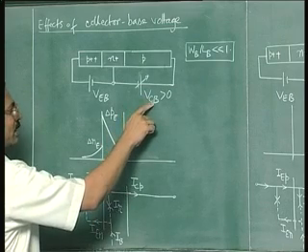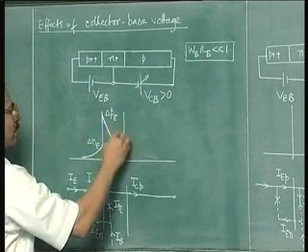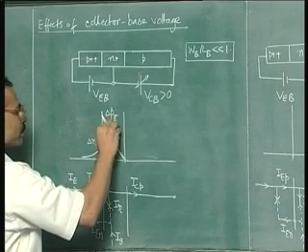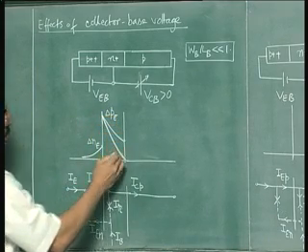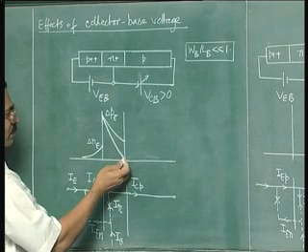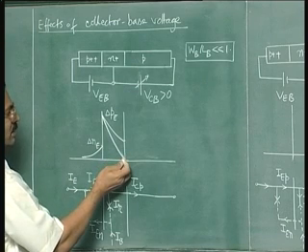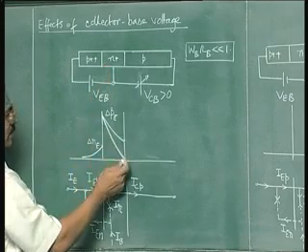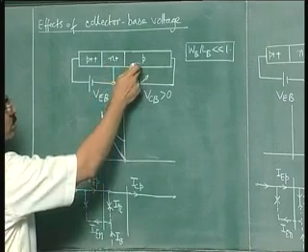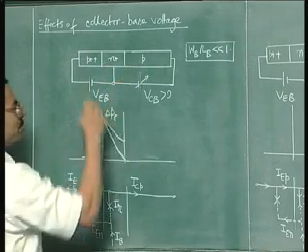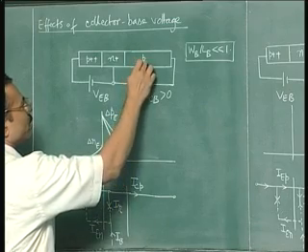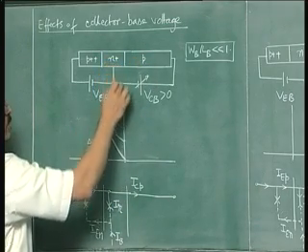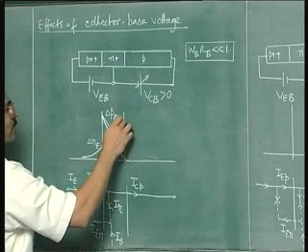If your collector base voltage is now positive, or there is a forward bias, you will have the following situation. The boundary value of the excess carrier concentration will increase on either side of the junction. So your hole concentration on the N side has increased and you are also going to have excess electrons on the P side, and since doping in the collector is lower than doping in the base, your excess carrier concentration of electrons in the collector will be more.